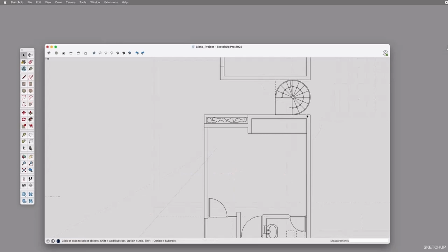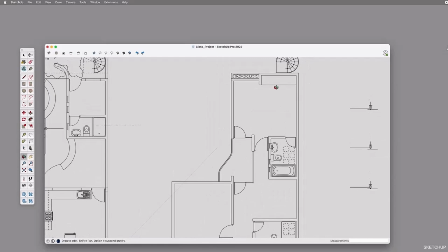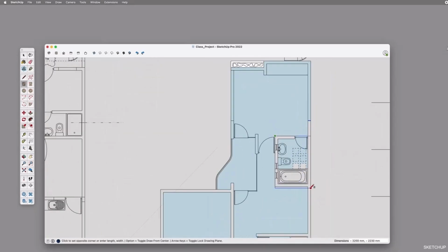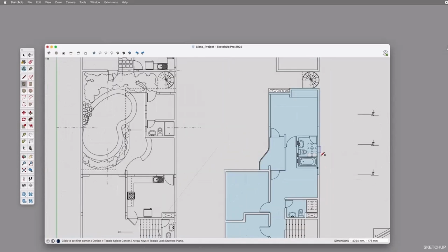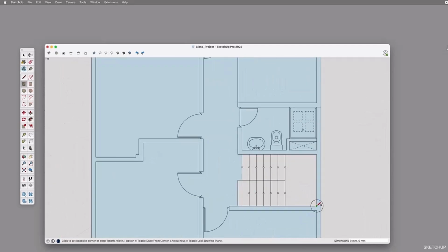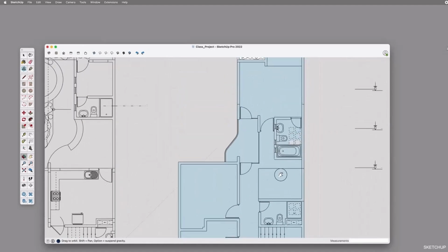And now to build up walls in the later stage, I do need a surface, meaning I need to get somehow my white surface back. I can use the line tool, I can draw over existing lines, I can try the rectangle tool. Sometimes it's a mix of both, really. There's no exact way of how to get the surfaces back, since files can be very complicated once they are produced. So with time, you get a better understanding if it's worth it to use the CAD file or if it just doesn't make any sense and it's better to create a floor plan by hand.